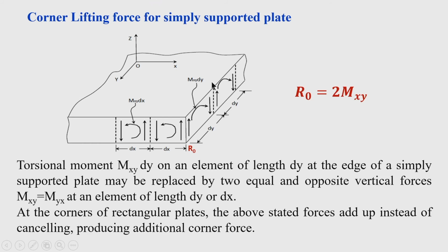Now, let us see what corner lifting force is. Corner lifting force is a force that is generated at the corner. How does it generate? You can see that the torsional moment Mxy dy, if we take an elemental length dy, can be replaced by two equal and opposite forces. So, if we do this at the corner, these forces will add up, giving an upward reactive force.